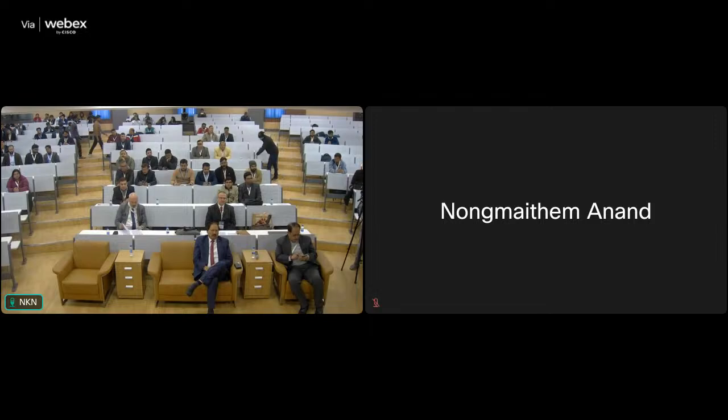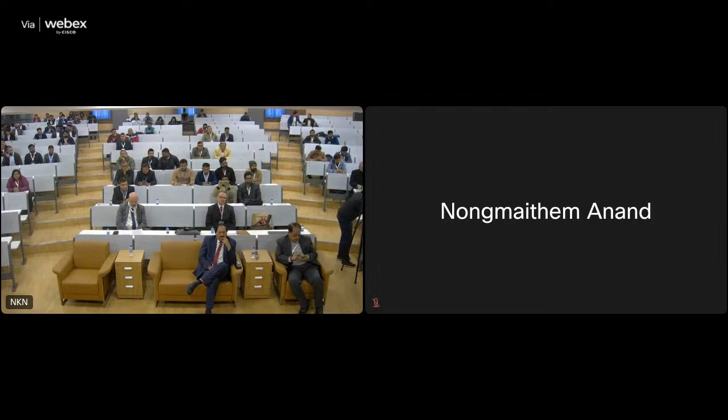So picking this point from his statement, I have tried to study a bit about this, how the rock bolt grouting can influence the rock mass quality surrounding the tunnel excavation. So what we can really presume is that improved rock mass quality shall help in reducing the ultimate pressure for which we have to design the supports, right? So the study presents the improvement in rock mass quality suggested by Barton. So what I have done is how various parameters of Q may be influenced because of the grouting of the rock mass.